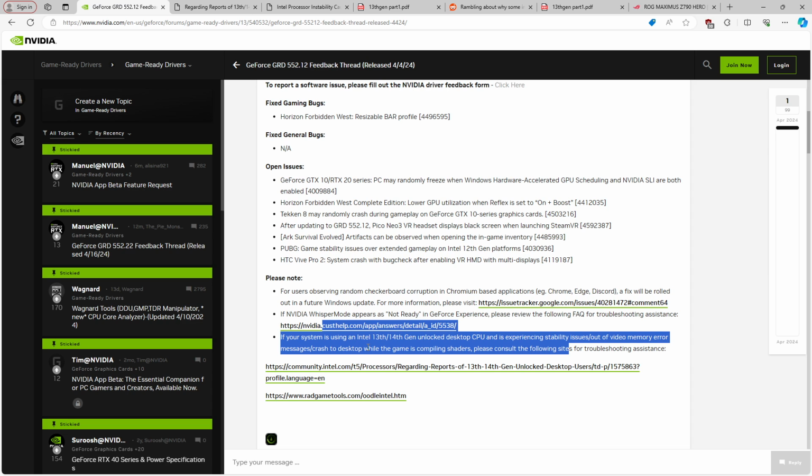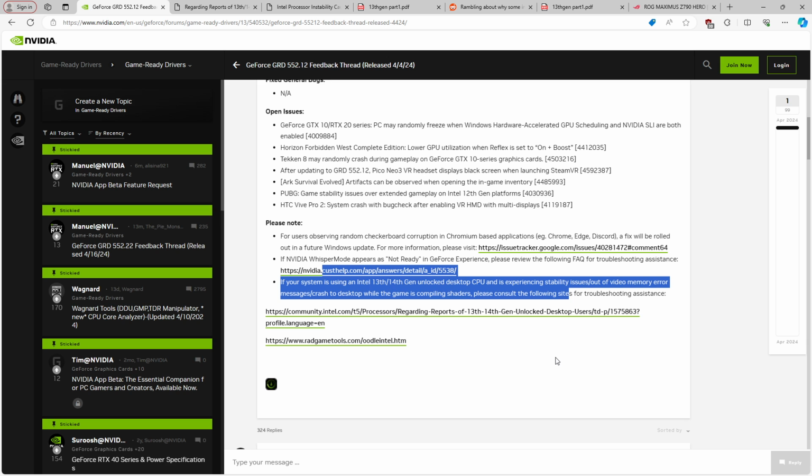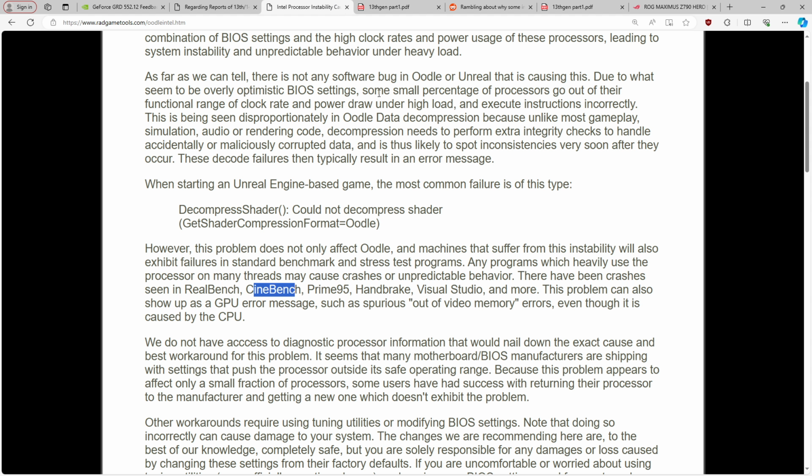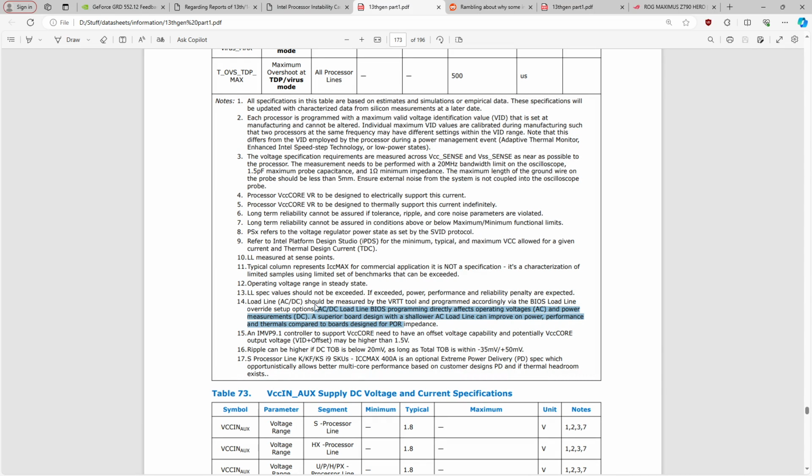Because they just say, here are voltage regulators you are allowed to use. These are the settings you are allowed to run them at. If you don't run them at that, we stop sending you GPUs. Also, you can't put too many power connectors on our GPUs either. Actually, you can't really do anything with NVIDIA cards without NVIDIA's permission. And then there's Intel, where it's like, yeah, we're just gonna set the load line. It's gonna be fine. There is absolutely no reason to not set this correctly.